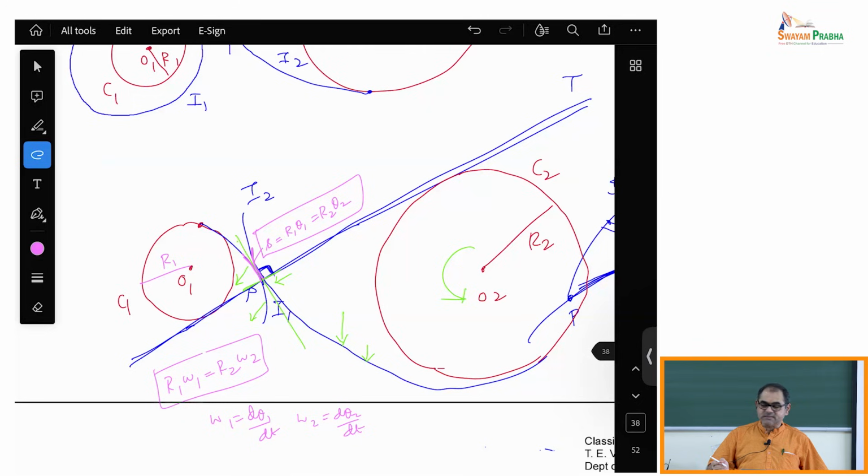It is just the reciprocal of the ratio of the radii, which corresponds to the fact that the faster the gear moves, the smaller the radius of the gear. This is the fundamental law that has to be satisfied by gears: the ratio of angular velocities of the two gears during transmission should be a constant. So that condition is satisfied here.